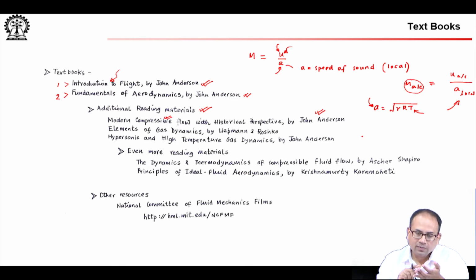So, it depends on the relative speed of the vehicle with respect to the surrounding air, but it also depends on the velocity at which these acoustic perturbations move in the vicinity of the aircraft. Essentially, you need to know the temperature, which will give you the speed at which these disturbances propagate, and why fluid mechanical behavior depends on that ratio is something that we will consider in subsequent lectures.